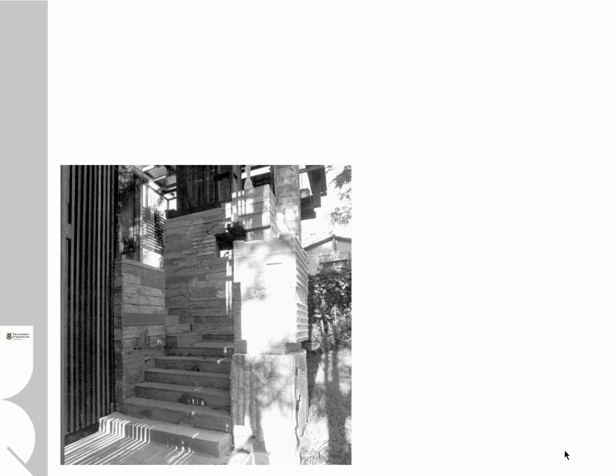Now there's the other approach, in which case you take on board the fact that the concrete's going to stain, that the formwork is going to be a little bit rough, and celebrate that in a way. This is a rather idiosyncratic project. It's the Highgate Hill house from Donovan Hill, quite an old project, and this massive concrete stair was made, in fact, the shuttering or the formwork was made from waste material from the site. So any demolition materials were kept, and they were used then to form the concrete.